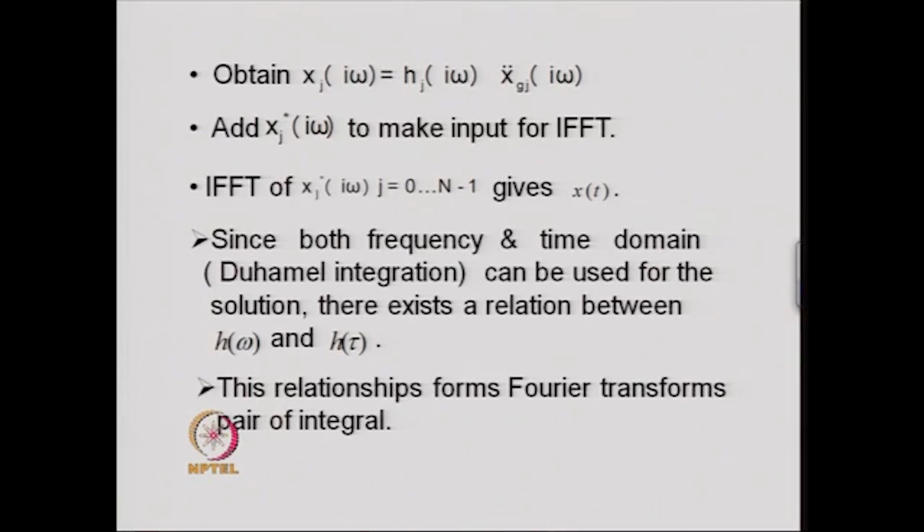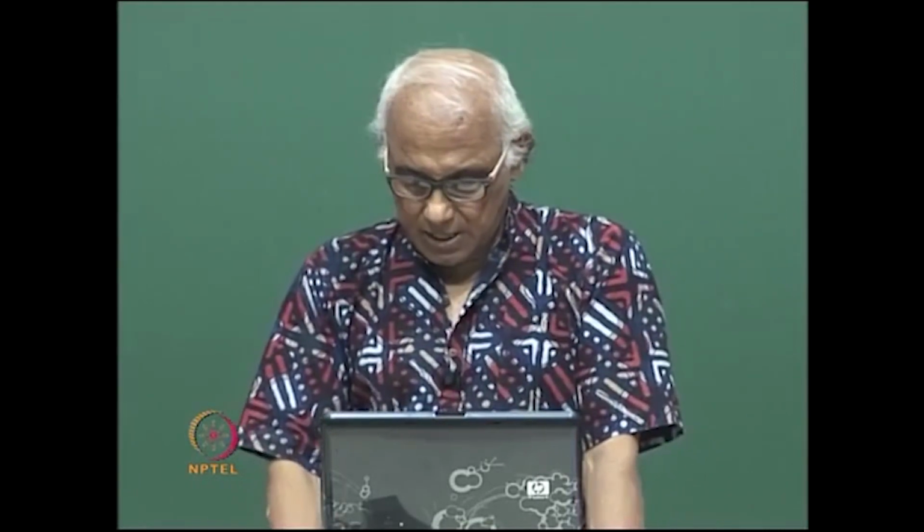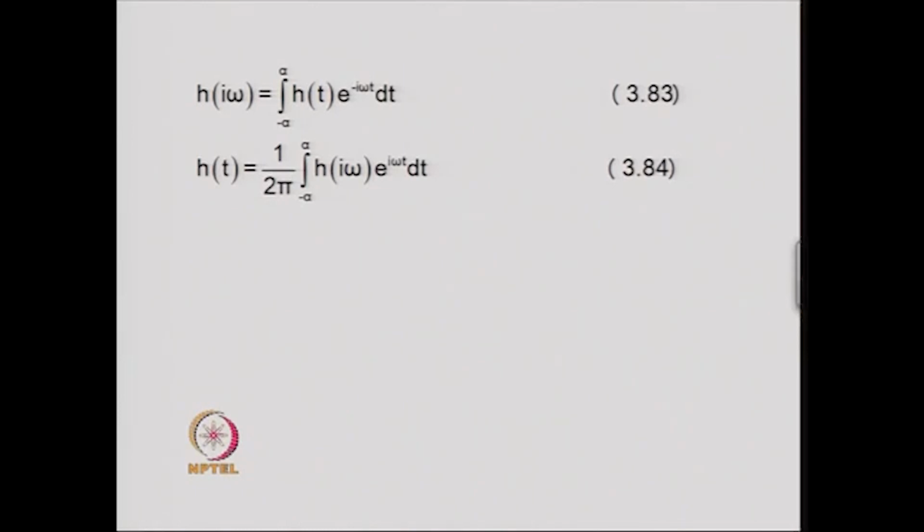Now, h tau specifically arises in the Duhamel integration, that is, for the unit impulse, the integration that we perform for obtaining the Duhamel integration is called h tau, and there exists a relationship between the frequency response function and h tau, which is nothing but again the Fourier pair of the Fourier integral.